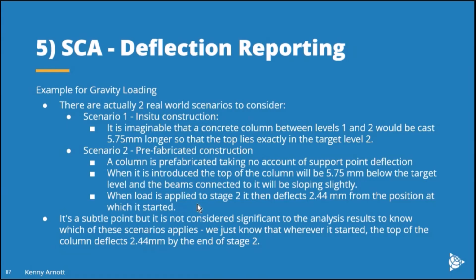And it's actually quite a subtle point, but in terms of the analysis, we really don't care which of those scenarios applies. All that we know at the end of the analysis is that wherever it started, at the end of stage 2 the top of that column has moved down by 2.44 millimeters. So if you built it longer, it will have still moved down 2.44 millimeters.